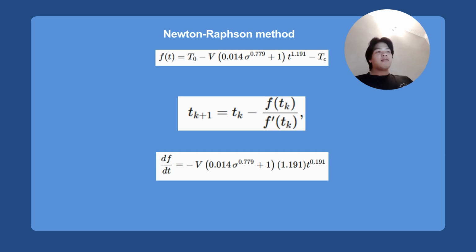It was solved iteratively using the Newton-Raphson update equation as shown in the slide. The iteration continues until convergence is achieved, yielding the critical failure time Tc, at which the residual ultimate load capacity matches the prescribed minimum safety threshold.